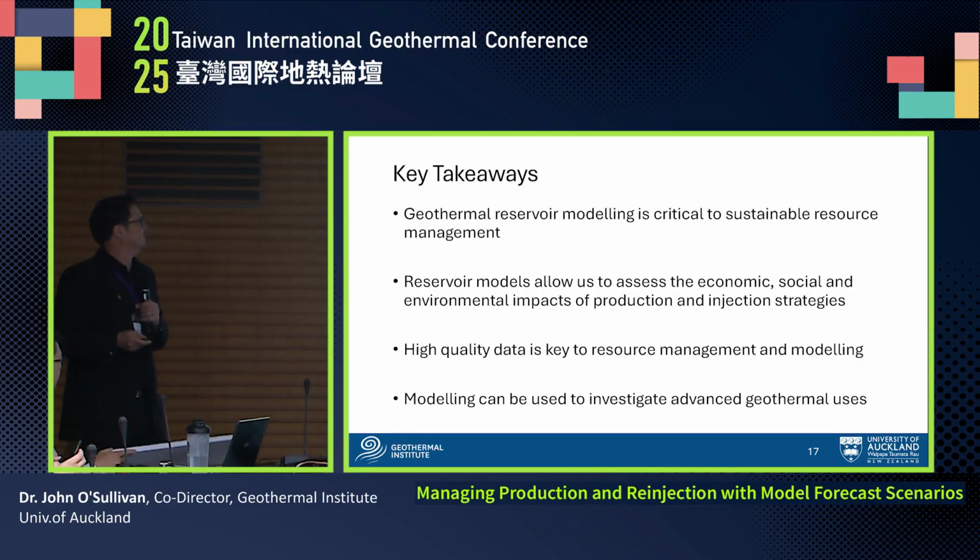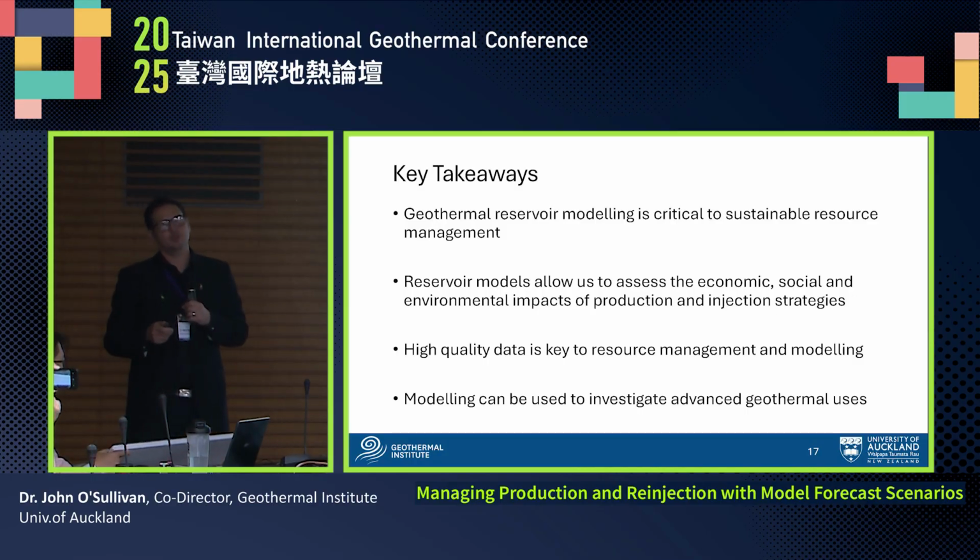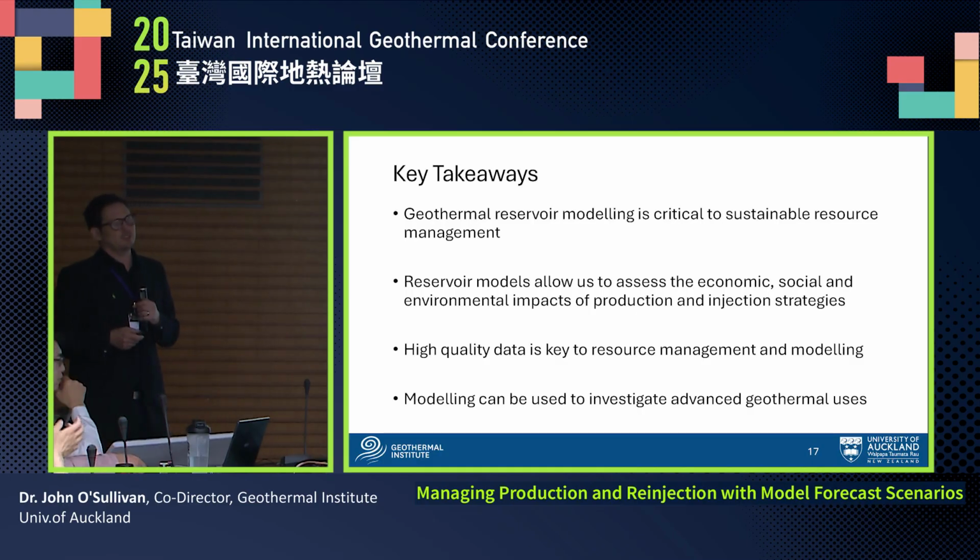So key takeaways: reservoir modeling is your critical tool for managing your resource, planning your production and reinjection, and it's going to allow us to assess those economic, social, and environmental impacts as well as the production and injection strategies. It's key to have good data, and as much data as early as possible. And as I've just demonstrated, we're now able to use reservoir modeling also to support these more advanced applications and geothermal uses as well.